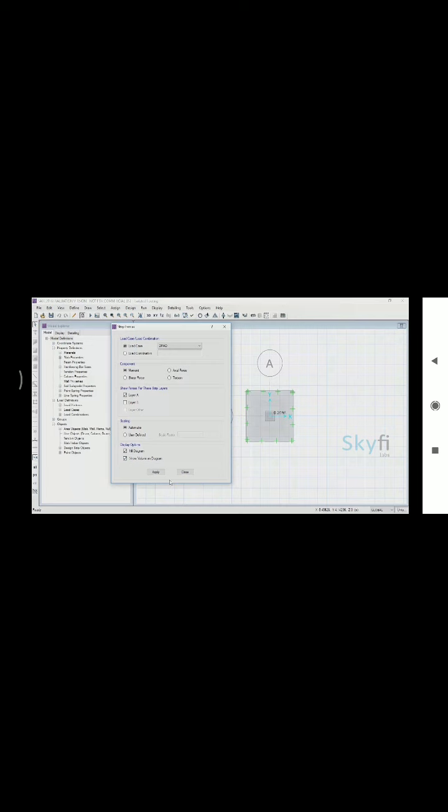Here as an example, the load case chosen is dead. The component selected as moment. The strip layer is A. And the display option is both Fill Diagram and Show Values. Click on Apply. The moment diagram for the dead load is displayed on the footing, over the strip layer A, along the X direction. Hover your cursor over the strip layer, and the moment values at each and every point is displayed.